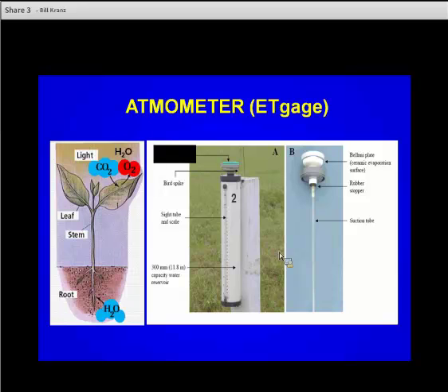So from my perspective, I would prefer to use the soil probe and use a core to do it, even if it's a piece of pipe that allows the soil to go up inside of it, rather than use a rod to pound down to get to that depth. I think you're going to find that the movement of water in and out of the soil is going to be much more consistent with what the bulk soil is doing if you do it that way.